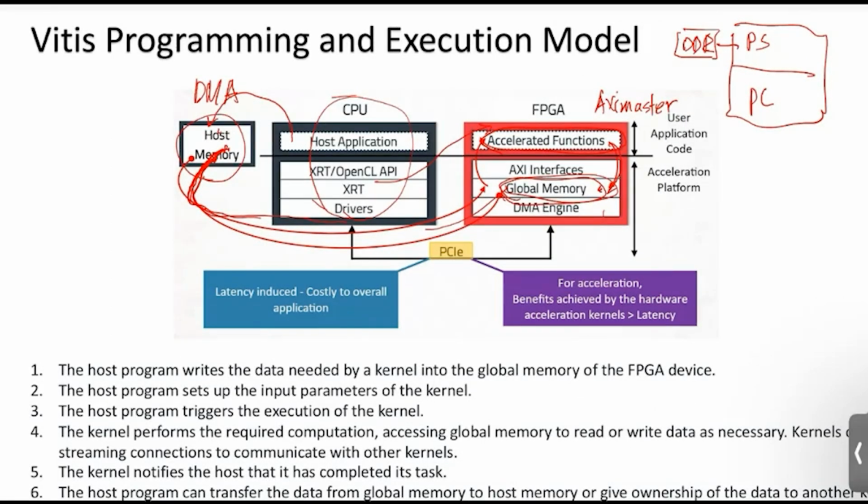Let's reflect on the PYNQ embedded case. Actually, the PL uses the AXI master to get the data from here. So this memory serves as the host memory for the PS program, and also serves as the global memory for the PL kernel function, which uses the AXI master to access the DDR memory.